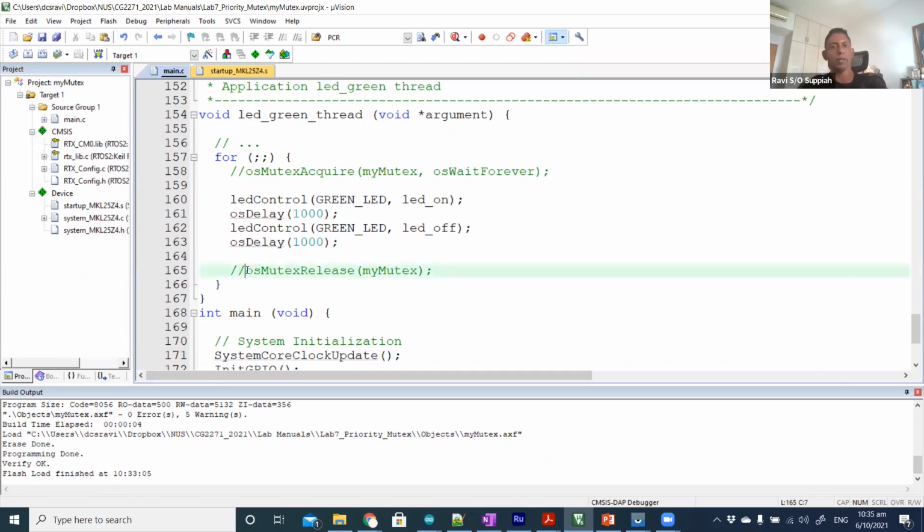When you and your friends are working together and one of you follows these rules correctly, but another person maybe is not aware that a mutex was created to control the LED or the PWM or something, and then the other person goes ahead to just access that resource without locking the mutex, then things will go messy.